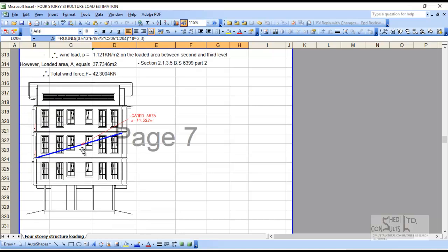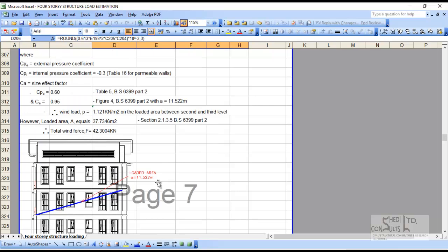Okay, between second and third is similar, 7.051. Oh, that's okay. That's nice. So the pressure intensity did not vary significantly because of the height. So the wind pressure is significantly height dependent, and it starts changing significantly when the height is greater than 10 meters, because the reference elevation for the wind velocity is at 10 meters.